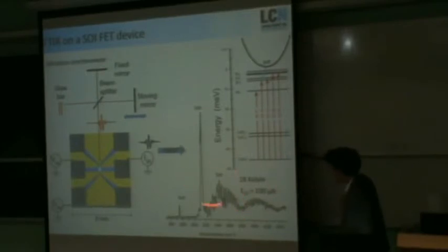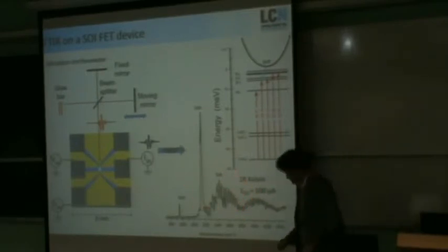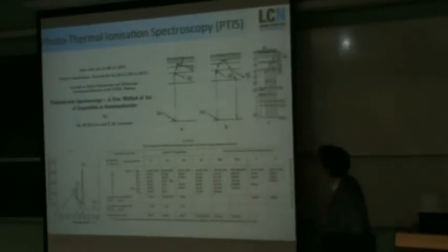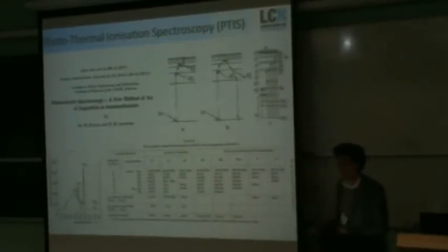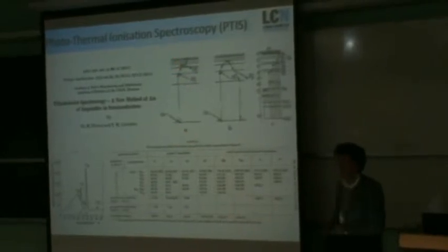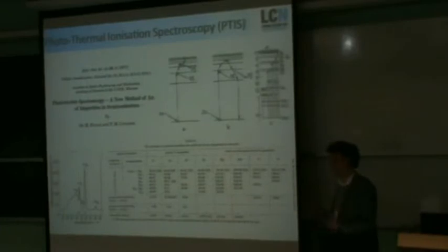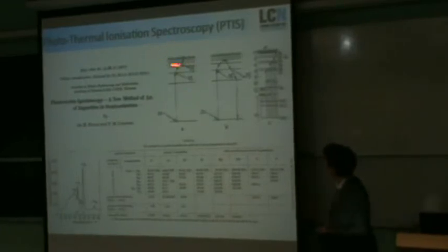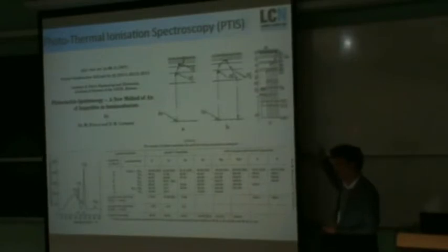So this spectrum is interesting, but it raises a few questions. Firstly, what's important here is how the actual mechanism works. Why do we actually see an optical response? This question is answered using the theory of photothermal ionization spectroscopy. Basically here, we're using the light to excite to an excited state, but then we're using phonons in the lattice to do the excitation all the way to get the electron into the continuum, and then you're left with an ionized donor, which changes the resistance of the device.